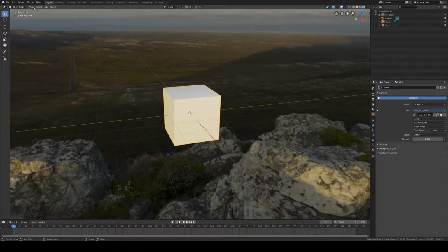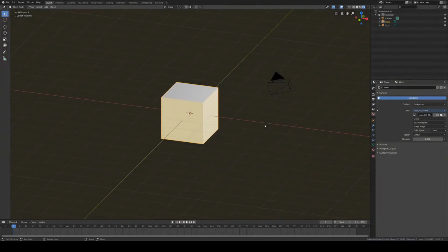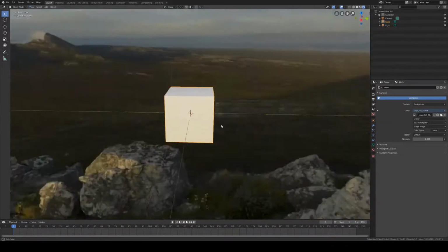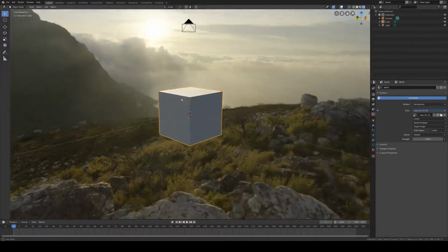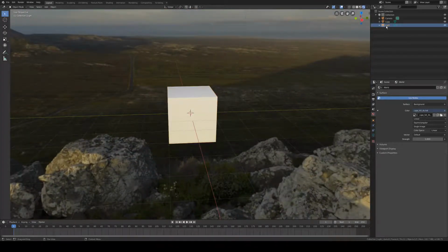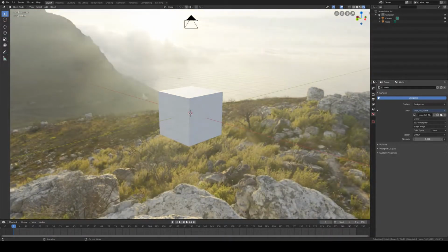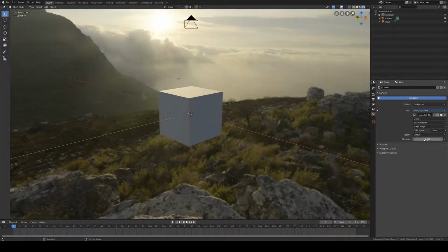However, if you are in orthographic mode, which is up here in view, perspective or ortho, it won't show you the background and you get this weird light flickering effect. A lot of times it will end up working in ortho mode while an HDRI is active, but you don't necessarily get the right effect. So you have to be in perspective for that to work correctly. As you can see, there's some sunlight over there, and it's properly affecting our light in the scene. I'm just going to remove the light that already existed from the standard scene so that we're getting a more accurate HDRI. You can scale this up to make it brighter or down to make it less apparent, but we're going to leave it at 1 for right now.